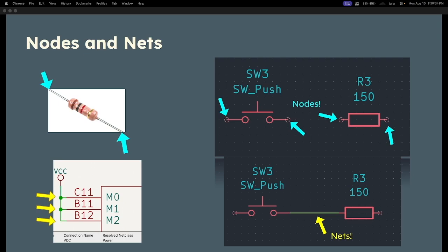The nodes basically represent the pins on your components that actually get connected. So in KiCad, anything that's a circle with a line intersecting it to the middle is a node. These are not nodes. I only bring that up because you once asked me if we were supposed to connect these, and you're not.